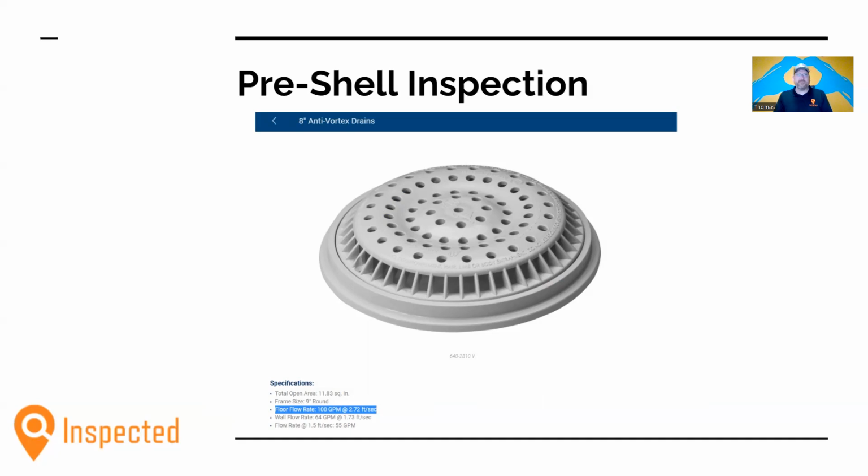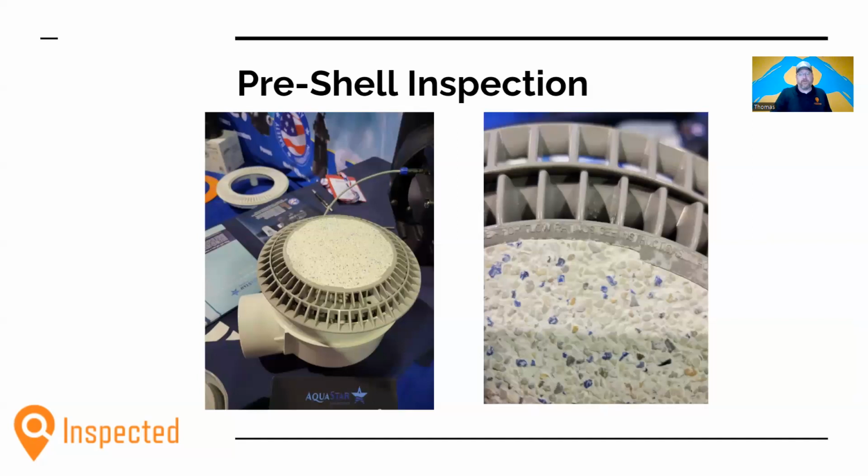If you've got a big old 2.7 horse pump on there with 3-inch suction and 3-inch returns, it's going to move more than 100 GPM, and you'll be in violation of federal law. So keep that in consideration with your pool construction. We'll be looking for your choice and options. There are main drain options that are unblockable, and they are prevalent across different manufacturers.